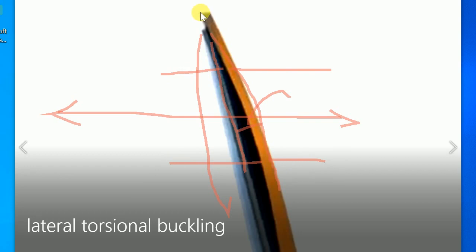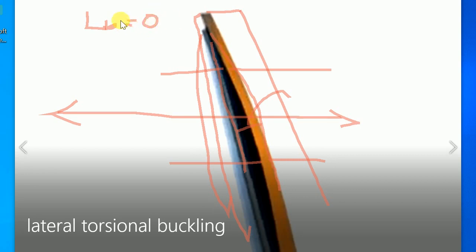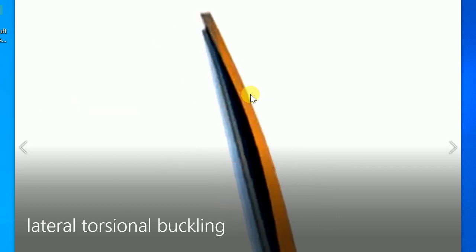And if we brace this beam throughout its length, like the one which I will explain to you, where the upper portion of the beam is inserted into concrete, that provides continuous bracing, and in that case your LB equals 0. That is your unsupported length. Your unsupported length equals 0. But if you don't provide continuous bracing and you provide intermittent bracing, I will show you this intermittent bracing, then your LB will be this length, okay?